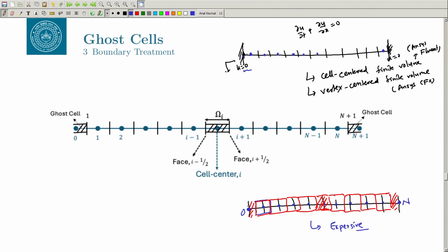So, what we do in this approach is we construct something called a ghost cell. You want the value of u equal to 0 here, and let us say you have some value at this point in this cell. Here let us say my u is 0.5, and here let us say u is equal to 1, and it goes down here also to 0.5. Let us consider a kind of symmetric thing. Now, you have to ensure that at the boundary my value goes to 0.